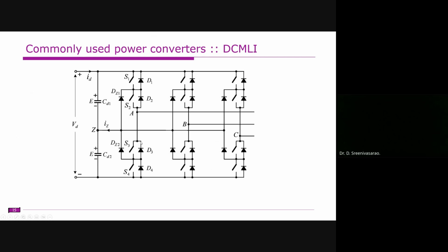Unbalance usually occurs due to deviations in the capacitor voltages. We expect that the top capacitor and bottom capacitor will charge uniformly. Small deviations like manufacturer tolerances, or currents injected into one capacitor and the other capacitor, and different turn on and turn off times, will produce deviation in the capacitor charge and discharge cycles, right?